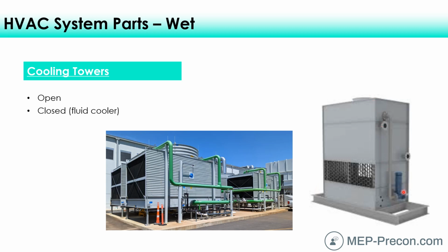And here's that little pump that just pumps water from the sump down here, and it goes back up to this distribution manifold that spreads the water throughout all the fill material. So we have this water, which is kind of cool, and it sprays over top this big coil. You can kind of see it's offset here because it wraps around a few times and comes back out here.